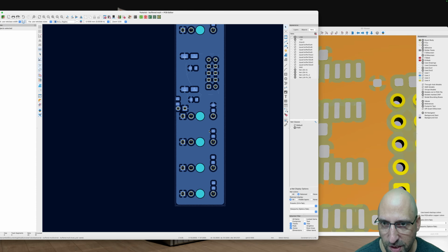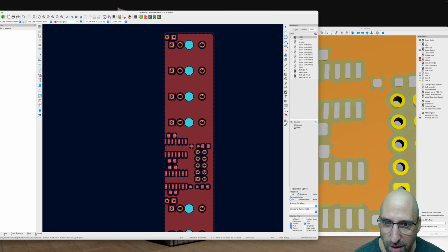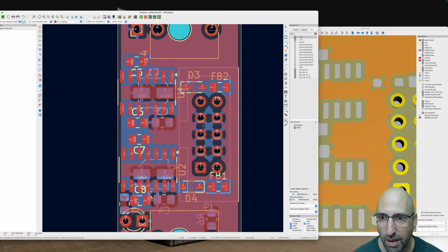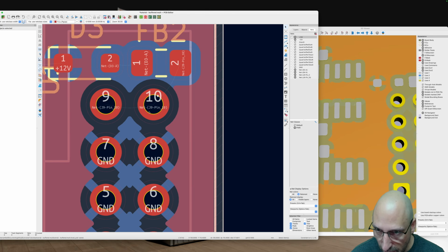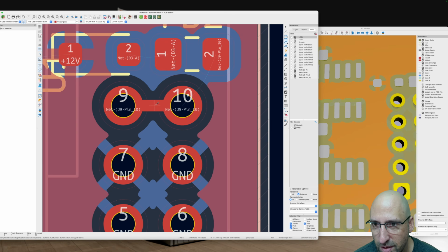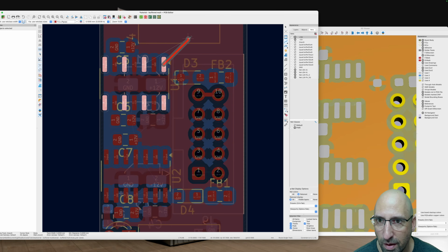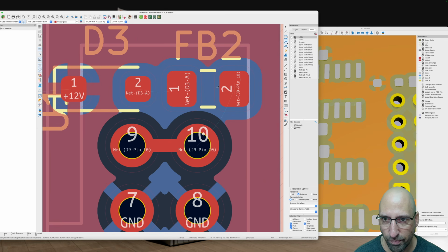So yeah, a bunch of things we need to connect, and as it happens, because we placed all our power circuitry over here, it's limited to this little space on the board. Okay, H. So let's draw some tracks. I'm going to hit X to start a track and draw it. And what you can see is the thickness of that track. Let's just draw any other track like input A. You see the difference in thickness, power, everything else, right? And that's because of our net classes.